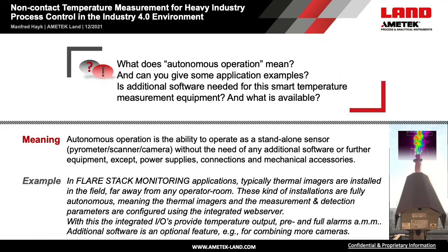With this example, I would like to answer the other questions. For example, in flare stack monitoring applications, typically thermal imagers are installed in the field, far away from any operator room. These kinds of installations are fully autonomous, meaning the thermal imagers and the measurement and detection parameters are configured using the onboard web server.